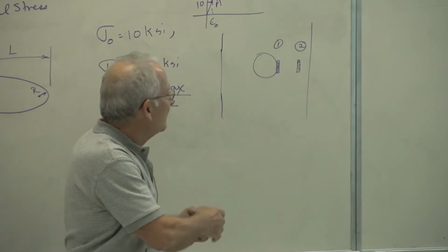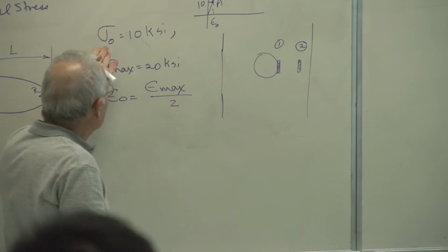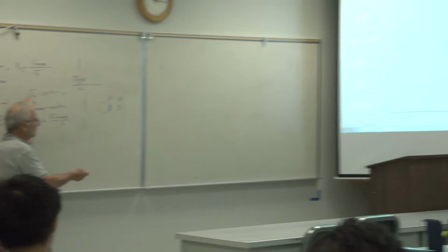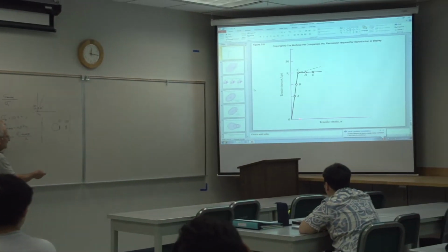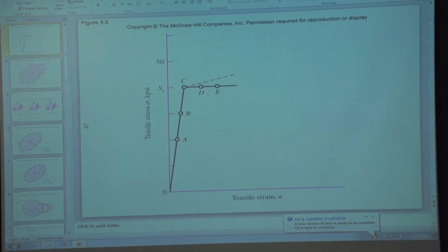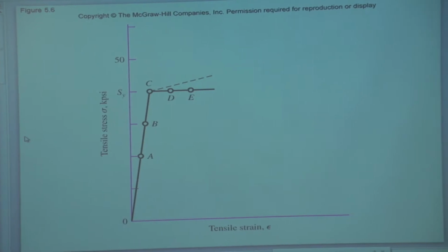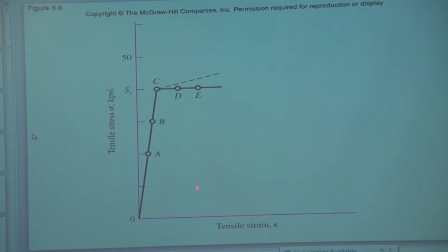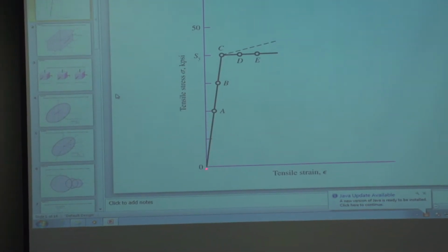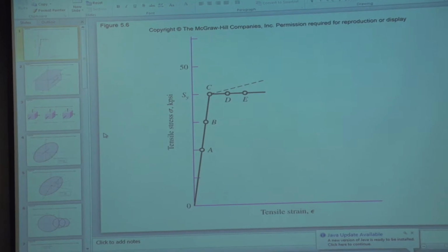So in the example that I just gave you, when we read sigma equals 10, this is the strain. Max, that's the strain, that's 20. So we read the strains from the strain gauge, go to the stress-strain diagram, and find the stresses. So long as the material is acting linearly elastically, if the strain is doubled, so is the stress.